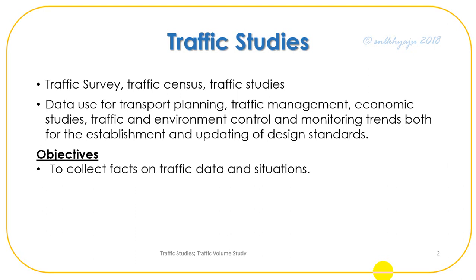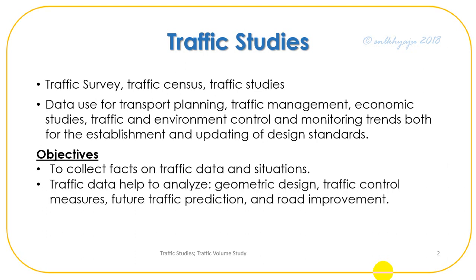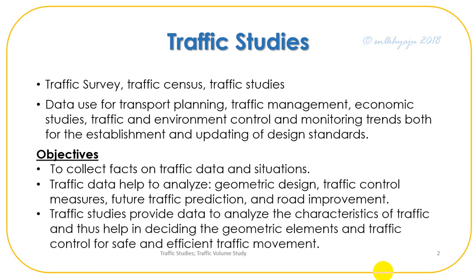Objective of traffic studies: to collect facts on traffic data and situations. Traffic data help to analyze geometric design, traffic control measures, future traffic prediction, and road improvement. Traffic studies provide data to analyze the characteristics of traffic and thus help in deciding the geometric elements and traffic control for safe and efficient traffic movement.